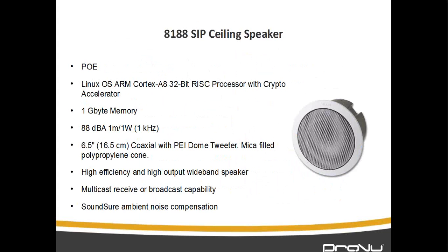The next one is an 8188 SIP ceiling speaker. So it effectively is the same as Algo 8180, but it is a ceiling speaker. Now, it is a bit unique in the sense that it is a fairly new product from the Algo range. It is running on an ARM Cortex, so it is a much more powerful processor. It is PoE. The other thing is it has 1 GB memory, so it does have a lot more memory than Algo 8180. So it basically means you can add more audio files to it.